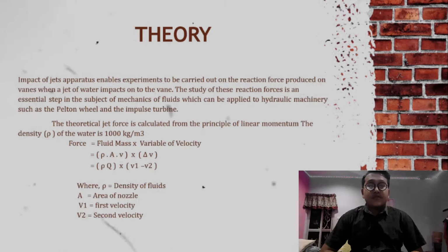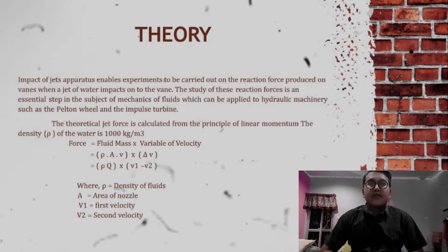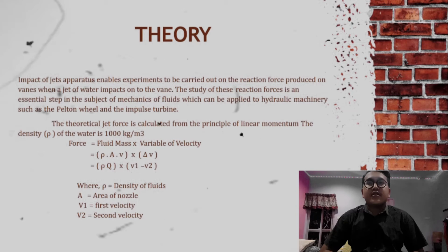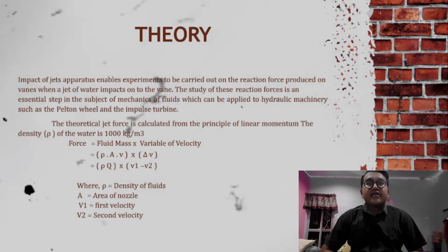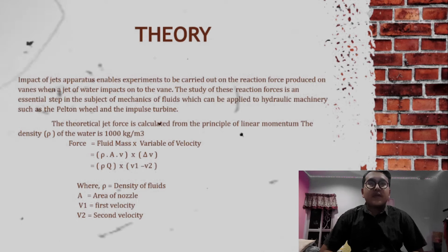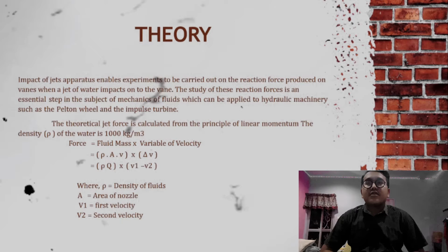So next, theory. The impact of jet apparatus enables experiments to be carried out on the reaction force produced on vanes when a jet of water impacts onto the vane. The study of this reaction force is an essential step in the subject of mechanics of fluids, which can be applied to hydraulic machinery such as the Pelton wheel and the impulse turbine.